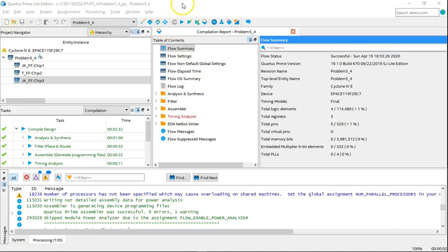So when you finish the synthesis process, you can inspect here now that you have 3 registers. That's a good thing to notice now, because you have 3 flip-flops in this design. So this means 3 registers that are perfectly well identified. Okay, 5 pins, and well, the logic elements is not that important, but the number of registers, yes, because they have to be clearly identified.